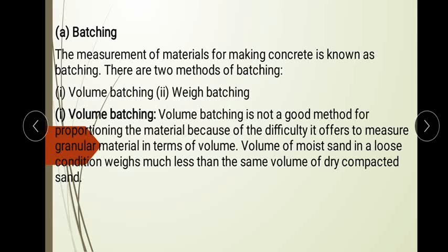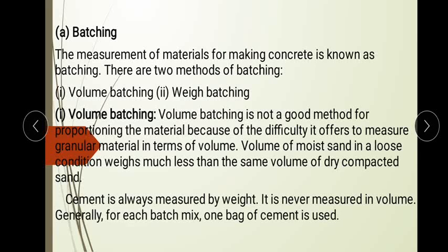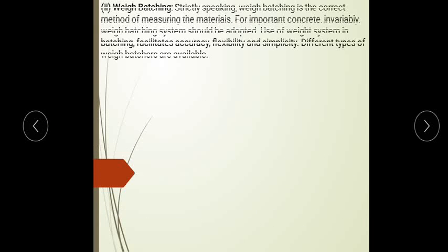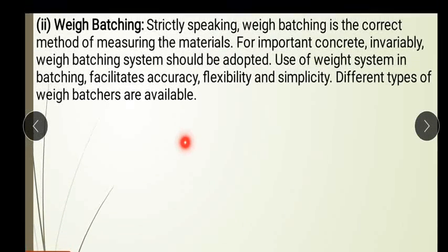Only with respect to volume we won't get the exact strength that we measure in laboratories. That's why we don't allow measuring cement, sand and aggregates by volume, because the volume of cement, aggregates and everything will differ because of the porous nature or something else.